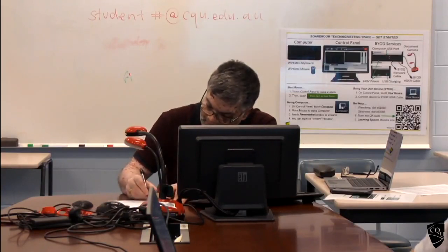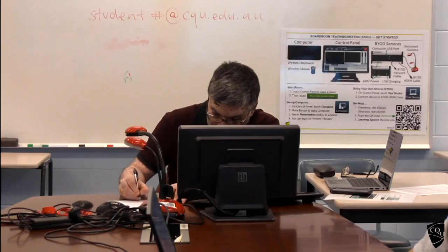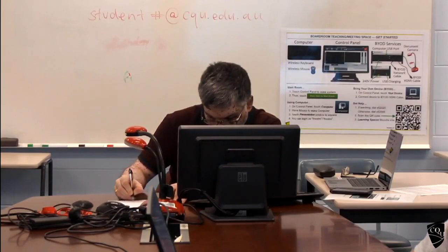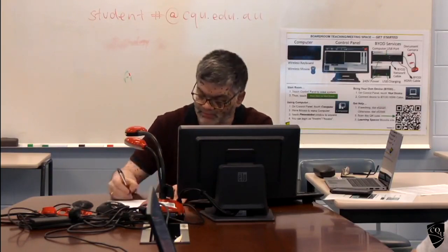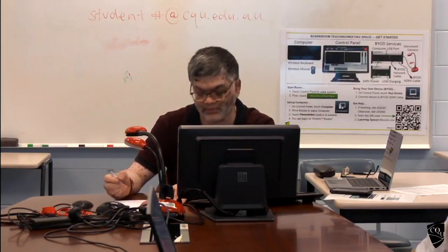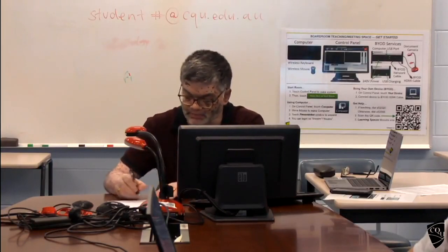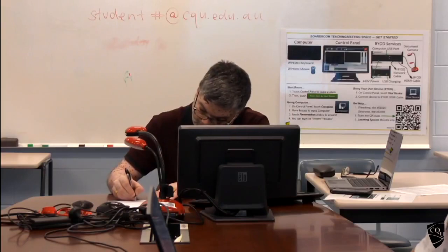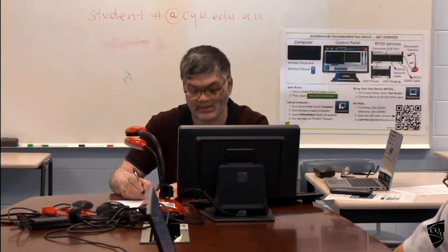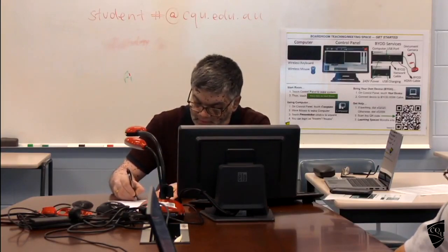So within that one we will have a column strip, and half of the middle strip. This is a middle strip. So we have half of the middle strip here and another half here.